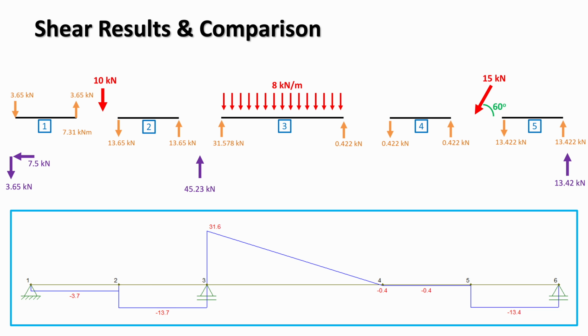The external loads in red and reactions in purple are included for reference, but the structure is not in full equilibrium here, as bending moments are not shown. Looking at the shear equilibrium in the MATLAB results, we can see that the forces balance correctly within each element, with changes in shear corresponding directly to the applied loads.